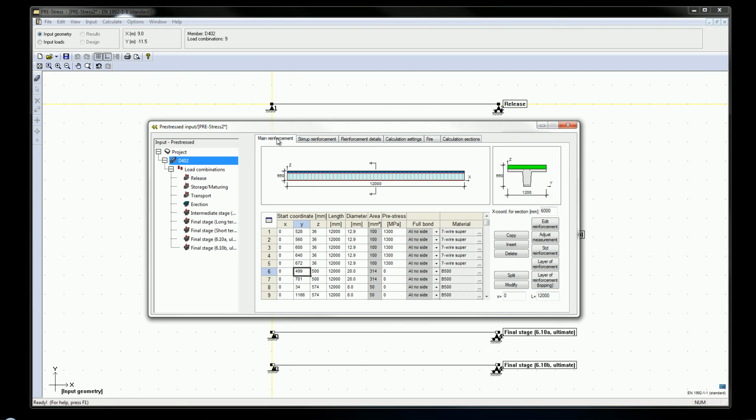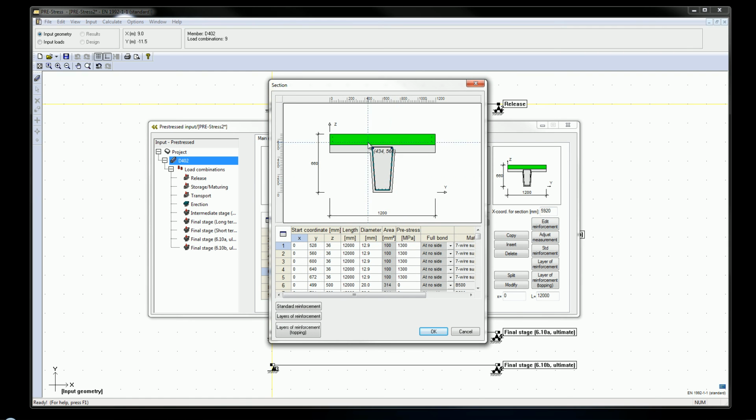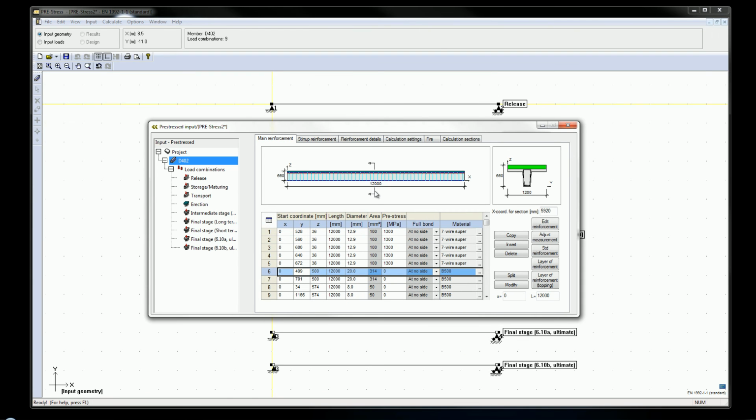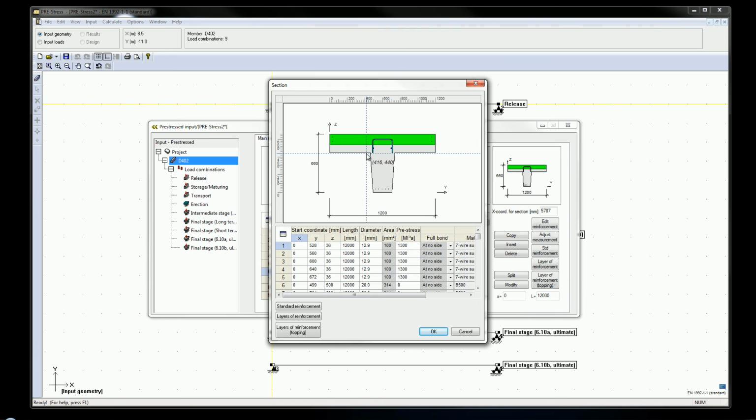And if we go now to the first here, we can see the normal reinforcement in the beam, and we should be able to see the reinforcement in the topping, which is actually connecting the beam with the topping. So any reinforcement that we see will be the area that's actually going through the joint here.